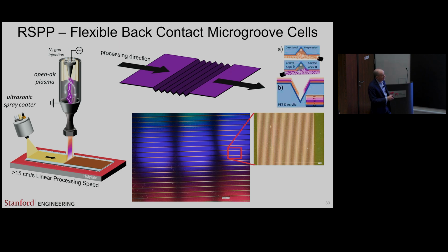And so then the back electrodes can all be connected on the back side, and that doesn't require the typical planar cells. So this is work that's underway at the moment. It's working well, and again, the advantage of these all back contact cells is also improved stability. Things like cracking of the perovskite layer itself, which is one of the ubiquitous failure mechanisms, is not as prevalent.